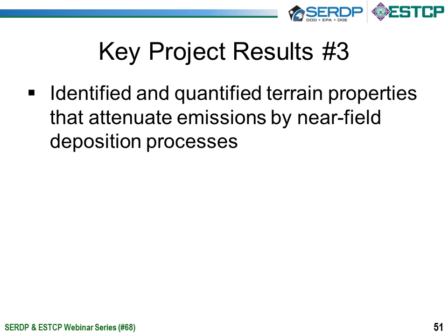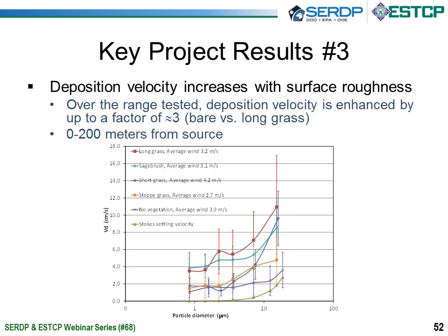So if you look at slide 52, you can see that the figure shows the deposition velocity, which is the scaling of how much the PM is interacting and depositing to the surface between the long grass prairie, which was in Kansas, down to a place with no vegetation. So you can see that the curves generally move up in scale towards the long grass, and altogether you're seeing that if you can maintain a fairly decent vegetation cover near the road source, you can influence the deposition factor up by about a factor of 3.